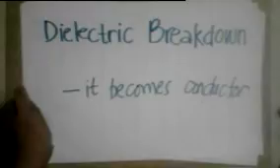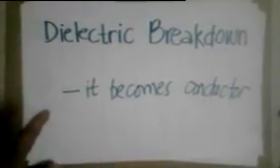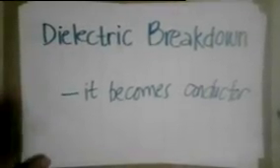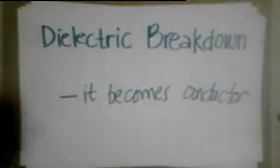Now this is also the reason why capacitors always have maximum voltage ratings. When a capacitor is subjected to excessive voltage, an arc may form through a layer of dielectric, burning or melting a hole in it. This arc creates a short circuit between the conductors. When this happens, the capacitor is rendered permanently useless. So when the arc creates a short circuit, the capacitor will be useless.